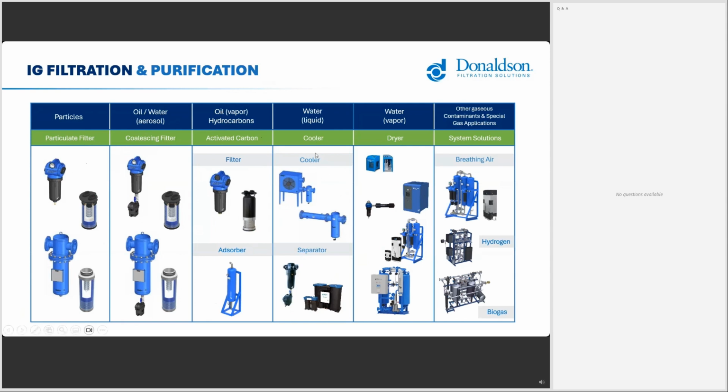Liquid water is very easy. You can just remove it by adding another cooling system, like a water cooler, an aftercooler with water as cooling media.